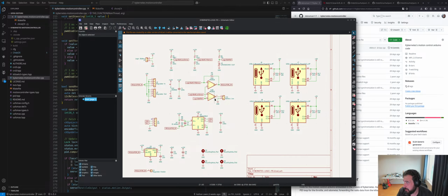I crashed this thing into a river once because the kill switch was just a soft kill switch, and the batteries got low, and it caused the microcontroller to just keep resetting. Unfortunately for me, I was using the Parallax HB25 motor controllers, and my Arduino was resetting. Those weren't. If those lose their input signal, they don't shut down. They just keep running the motors at whatever it was. So I completely lost the ability to shut the robot off, and it just ran away and ended up driving into a river. So I'm still scarred from that.